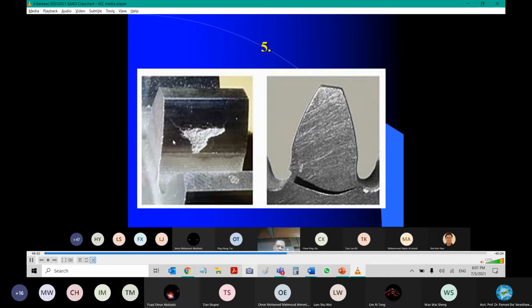Whereas on the left-hand side here, this is pitting of the surface of the gear tooth, actually. So it doesn't break, but there's a sign of shear failure because the contact stress is very high, and it causes shear as time goes. But this is certainly bending breakage. It is a break like that. It will fall off. Okay.